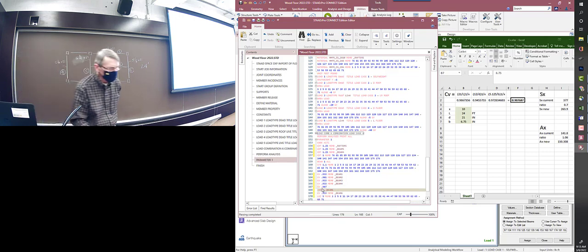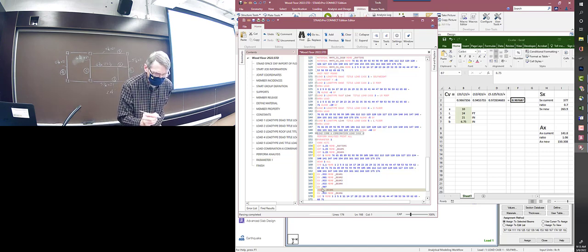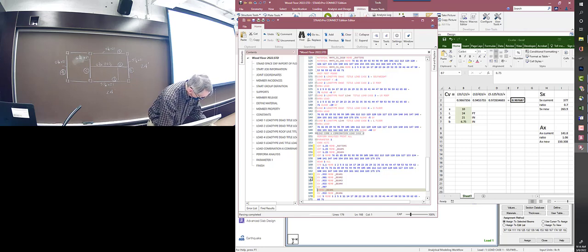I've gone through and set the things you want to set. We set the CD for the ones that are carrying a roof load. The others all carry a floor load, the 1.0 control, so I don't really need to worry about that. This is CF. That was the size factor we put on last time, hopefully for the rafters and joists. Oh, right, and we changed the size of them. All right, we've got to correct that then. What do we make them?